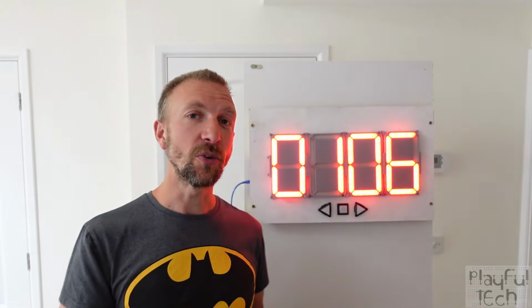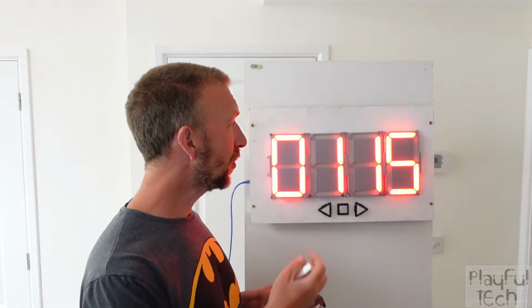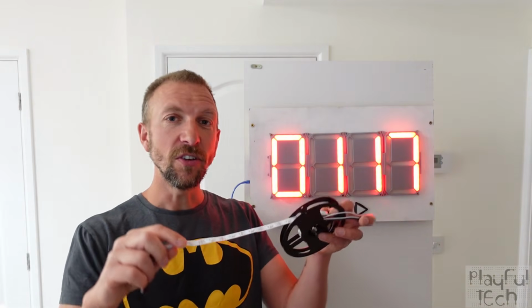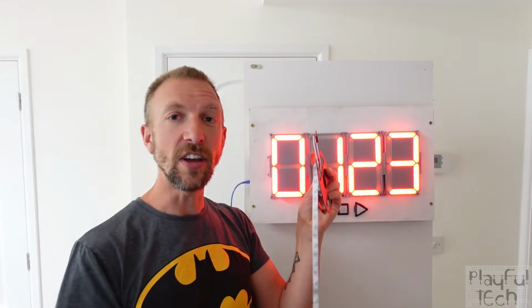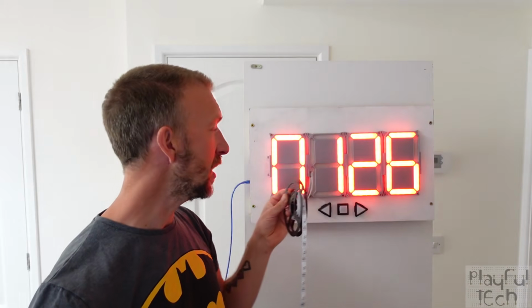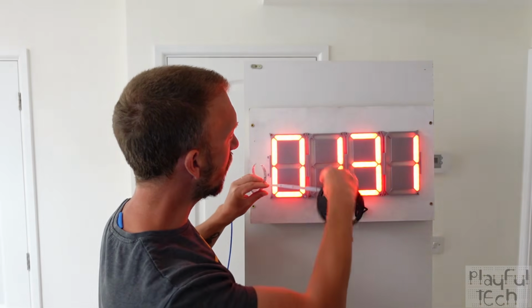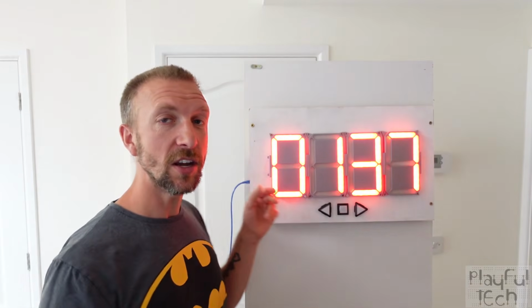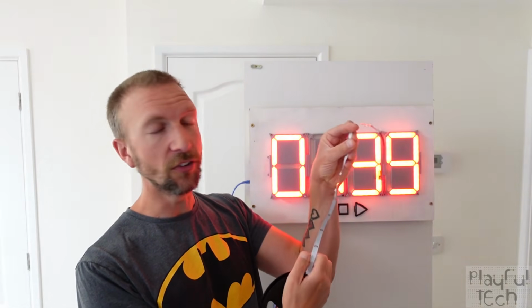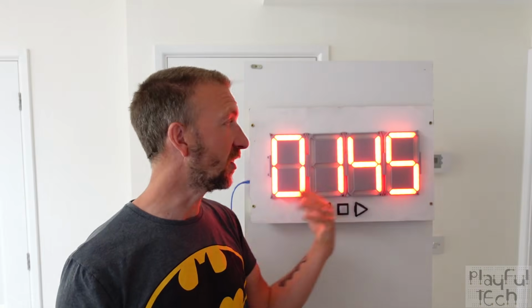So the approach I took was to create something that was easy, was cheap to make, and was scalable to a large size. And what I did was I've created this display using a programmable LED strip such as this. So this is a WS2812B or Neopixel display. And I've simply coiled it around into the shape of the digits of a 7-segment display here. Then I've got an Arduino which is controlling which sections of the strip to light up to correspond to each of the different segments, and that can make any digit appear.